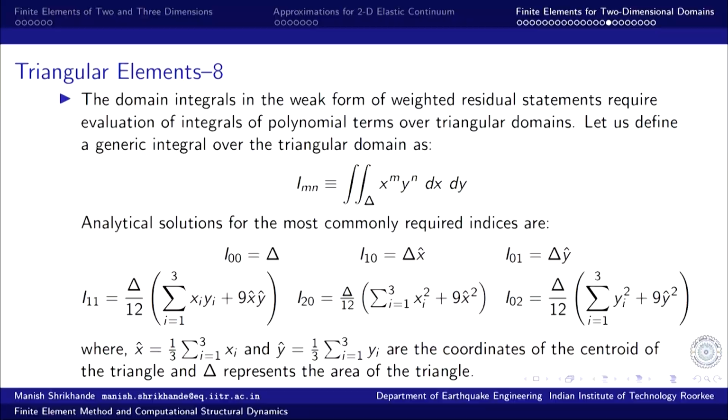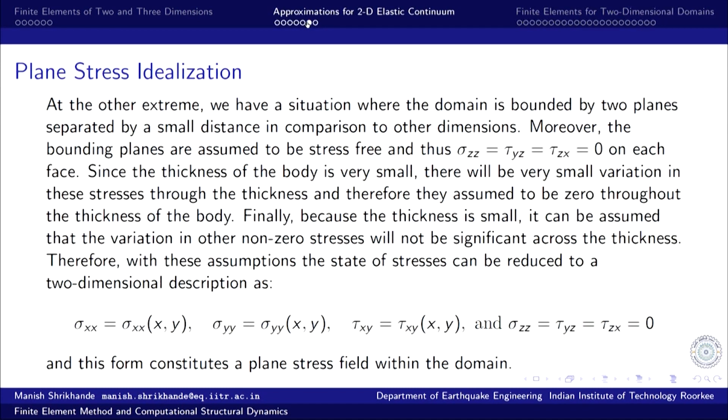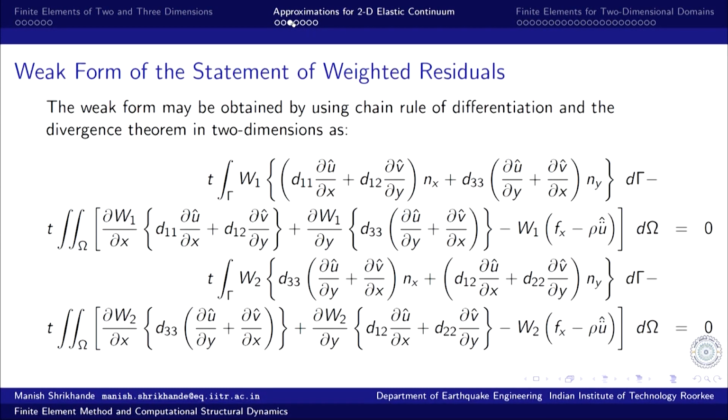Eventually, after all that we do, we need to evaluate integrals of this form. So, we need to evaluate these boundary integrals for each element. W 1 will be replaced by one of these interpolation functions N i, N j, N k, whatever.